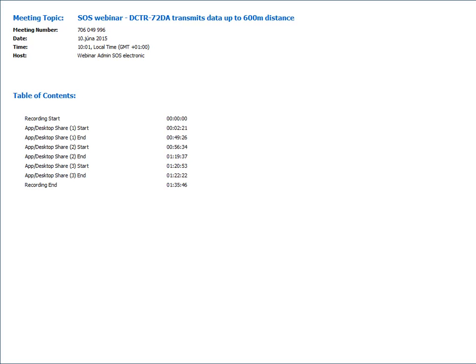And then when you have your own product, you have to do your own certification. But the certification will be much easier because we do the pre-certification. So actually, the certification of the radio part of your device will be very easy. Okay, and the other question is, what is the temperature range the modules are working in? We support the industrial temperature range, which is -40 to +85, if I'm not mistaken.